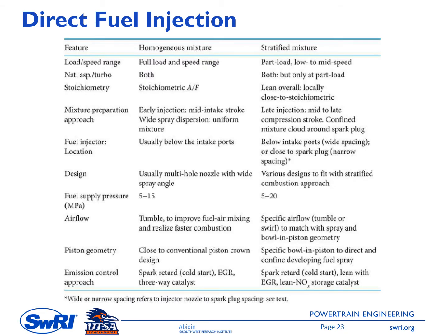As has been mentioned in the previous slide, with the direct injection, we can control this system to produce a homogeneous mixture at the end of the compression stroke, or a stratified mixture at the end of the compression stroke. So at the end of the compression stroke, here is the event where we have the spark ignition process. To have a homogeneous mixture, the fuel needs to be injected during the intake stroke, while for having a stratified mixture, the fuel needs to be injected during the early phase of the compression stroke.